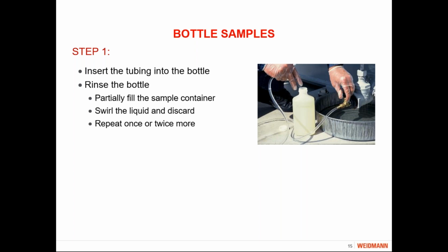And what we recommend is you fill it up, and not all the way, just maybe a couple inches into the bottom of it. Put a little oil in there, swirl it around real good, and dump it out into your catch basin. Do that a couple, 3 times. Make sure that there's no debris in there, no visible water bubbles or anything like that. If you do this procedure, you'll generally be assured that you've got a clean bottle to take your sample.